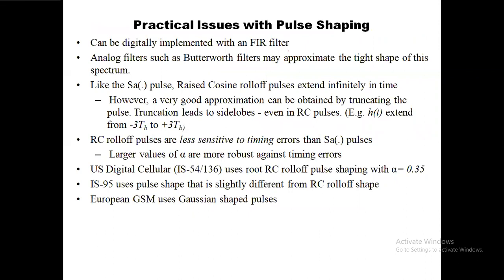So pulse shaping filters are implemented with FIR type filters, or analog filters such as Butterworth filters may approximate the tight shape of this spectrum. Like the sinc pulses, raised cosine pulses extend infinitely in time. So we have to make some approximation, and we need to truncate it.